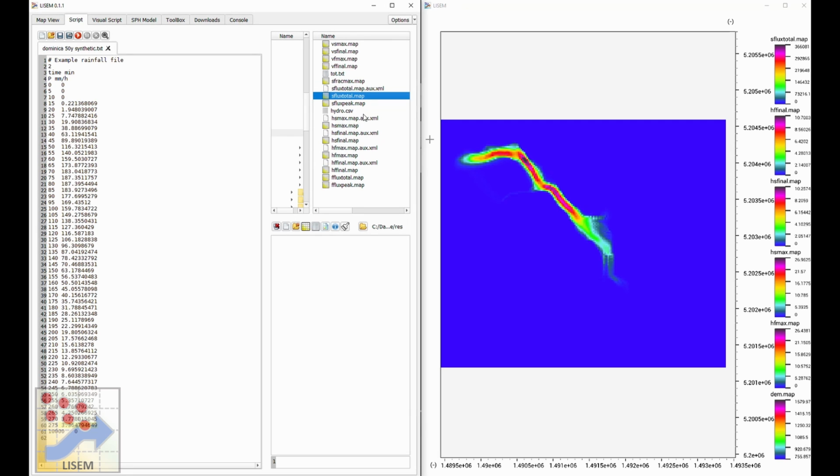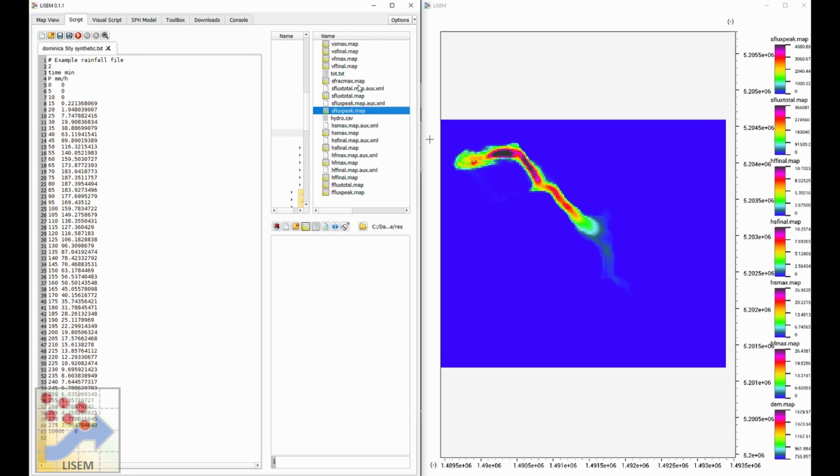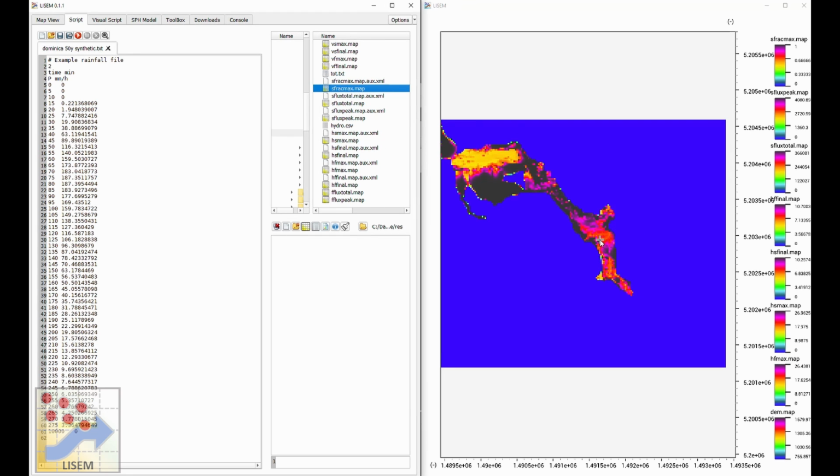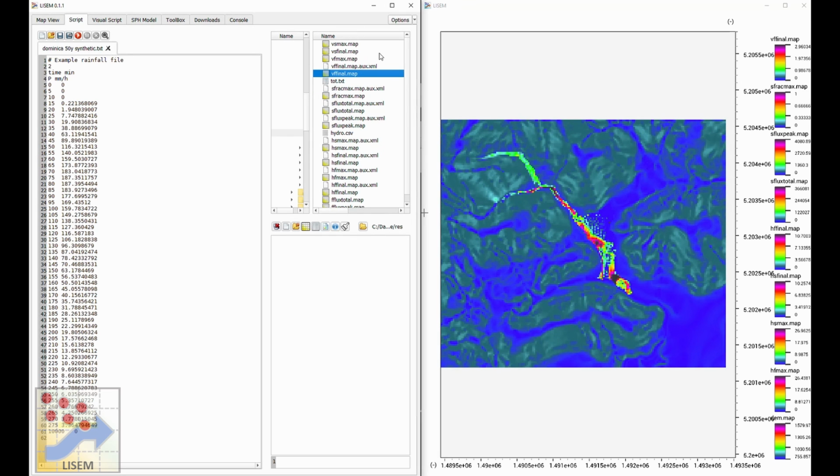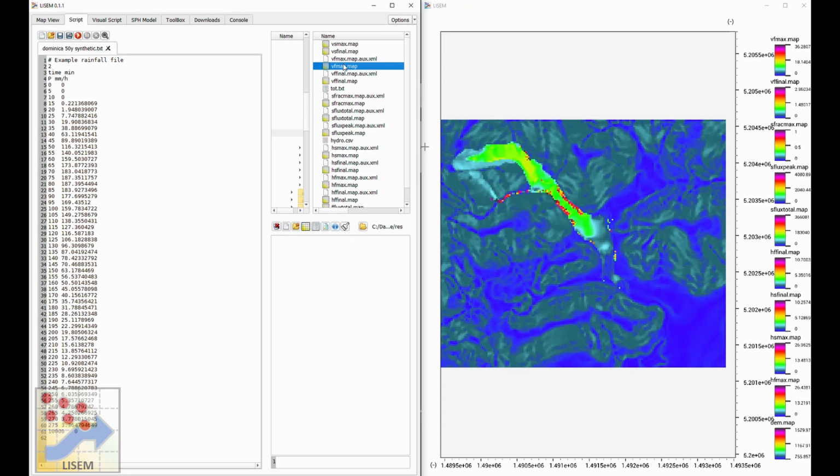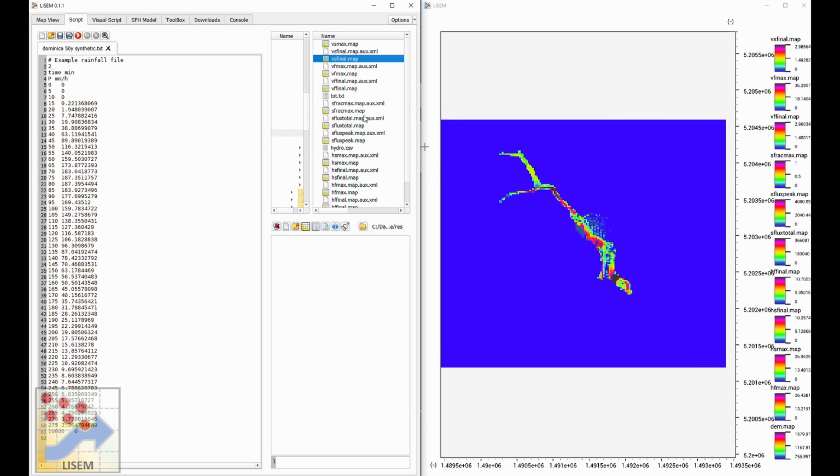Then we can get some information about the total fluxes, the peak fluxes, the maximum solid concentration, the velocities near the end, and we see that the main body of the landslide has lost its velocity there. The maximum velocity goes up to quite high values, but again, landslides run out, so that's quite typical. The final solid velocities are pretty similar to the final fluid velocities because it's such a mixture that moves together. So this is some of the output that is typically there.